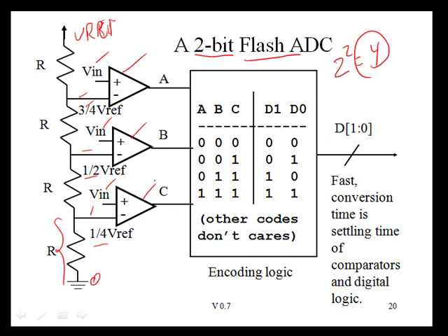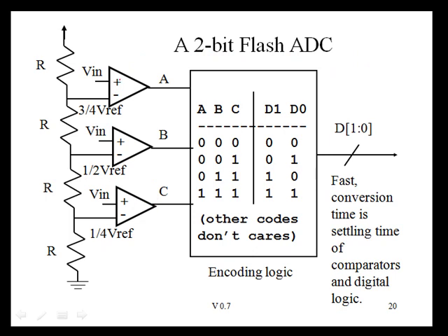Note that the positive terminal of each of the comparators is tied to Vn, while the minus terminal is tied to each reference voltage for that particular bin. This is going to do the comparison of Vn against all of these various reference points in parallel. Let's take a look at what the values of these comparator outputs can be as the voltage rises from 0 volts up to VREF.